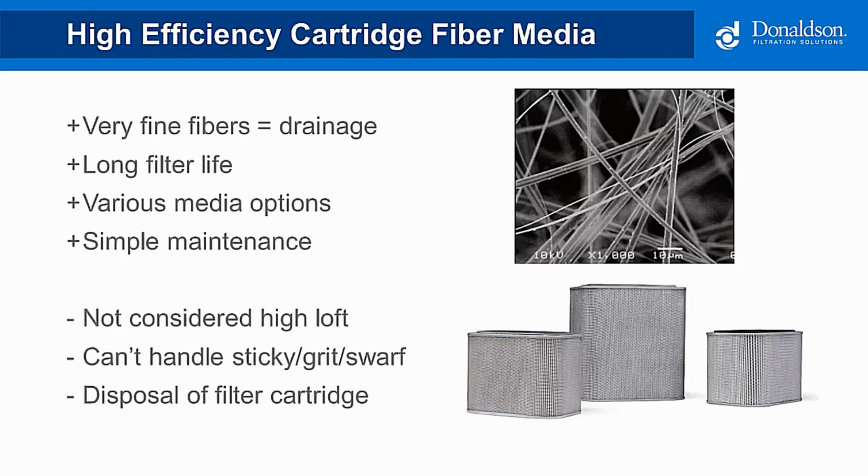The best performing mist collectors have filters that are designed for modern machining and are cartridge collectors. These are a combination of polyester and glass fibers for the primary filtration stage. As shown in the image, the polyester fibers are larger and drain well, whereas the glass fibers are smaller and provide higher efficiency. The fiber combinations vary overall, but these have proven to deliver high collection efficiency, sometimes in the high 90s in many processes. They also provide much longer filter life, often in the thousands of hours depending upon the application.